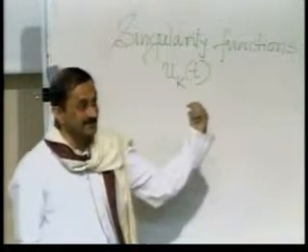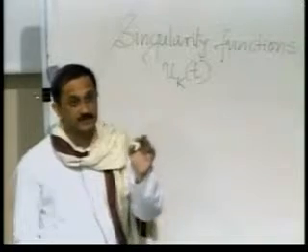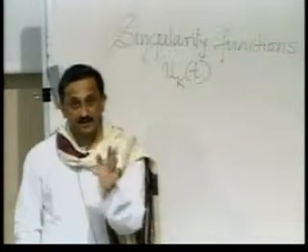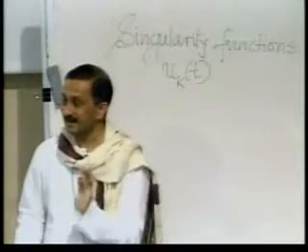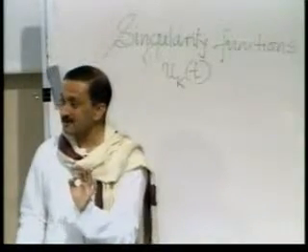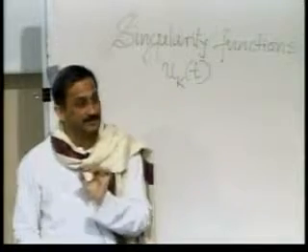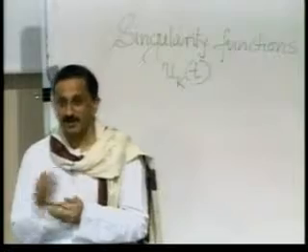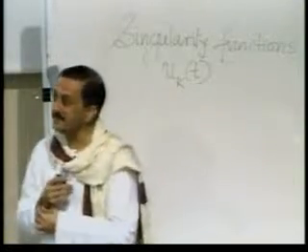This is one of them. If you look at the unit doublet, when it operates on a function that is constant after a point in time, it behaves correctly. But if it operates on a function that is constant for all time, then there is this problem of non-uniqueness when you go the other way. So it's not quite inverted by applying a running integral.